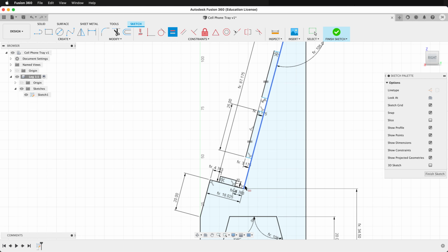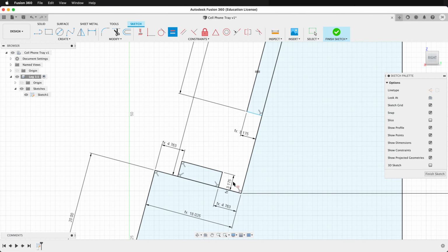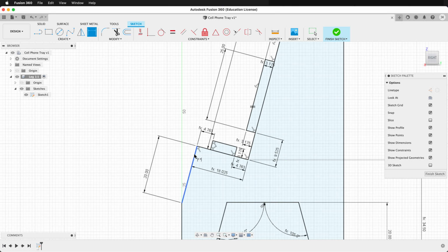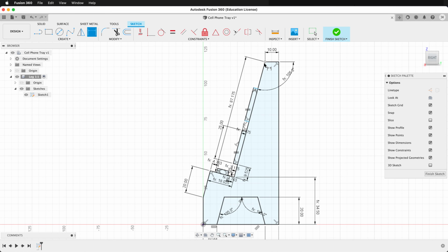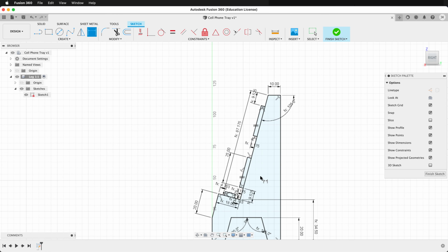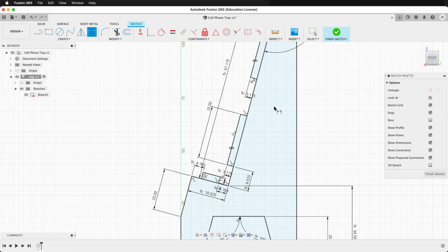So let's define this distance down here. So we're going to have ply here. So that takes up at least 1 ply. And then we'd like to have some distance before the plywood. So let's go ahead and press D. And we'll go from this mark here to this mark here, and we'll call that ply times 3. And it's nice to have a symmetrical piece. So let's come up to the top here and click this dimension and this dimension, and we'll say ply times 3. So now once again, we have a fully defined sketch. Everything is black. So that's great.